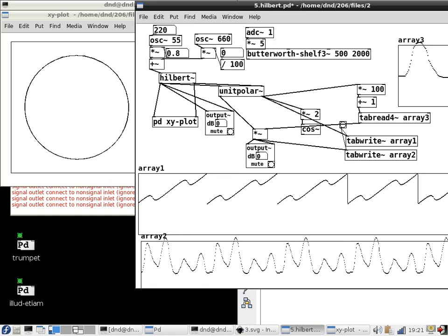And then give myself controls over it, but basically just make a waveform out of these cosines. It would give me the exact waveform if I just fed it a sinusoid, but when I fed it something that had harmonics in it, it would be doing AM and FM on that waveform. And when you do AM or FM on a carrier signal, if the carrier signal is a linear combination of simpler signals, the result is just a superposition of the original things. So FM also is linear in the carrier waveform, but not linear in the modulator.